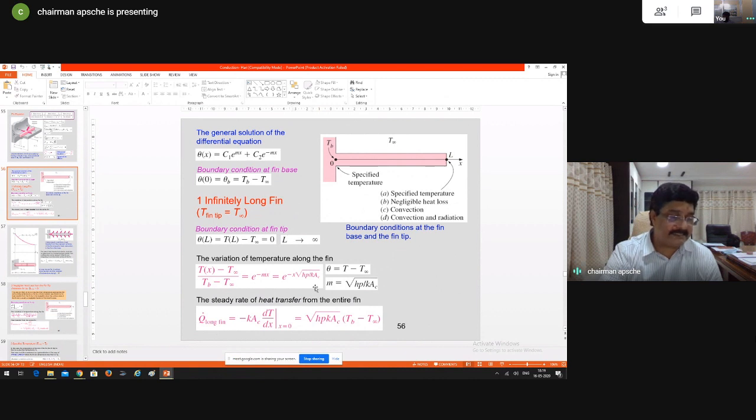When we place a cylinder tangentially to the plate, how to study the heat transfer for such fins? Cross-section area will be varying continuously. I said there are two types of fins. One is a constant cross-section area of the fin. Another one is a varying cross-section of the fin, like a triangular fin attached to it. So the approach is altogether different.